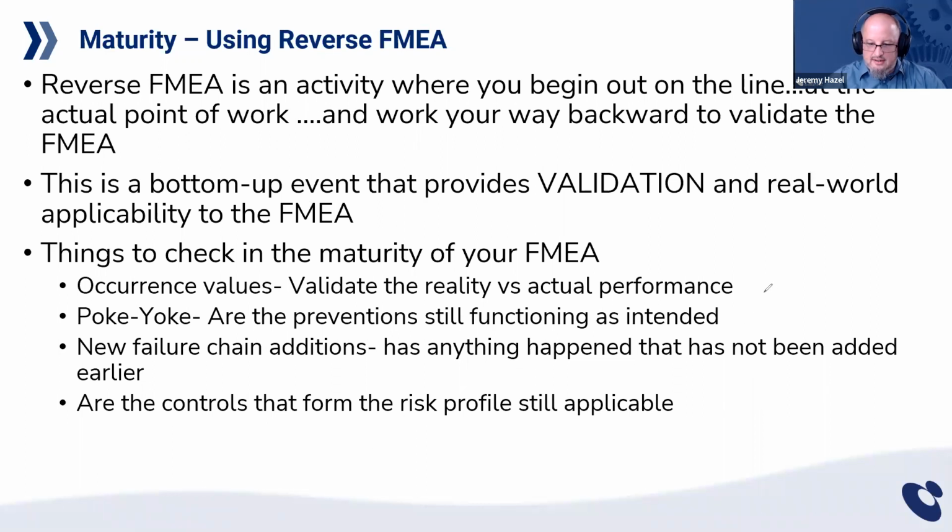Occurrence values. Validate the reality versus the performance. Poka-yokes, are they still functioning? Are they still being challenged? Are they working the way that you intended when you developed them? New failure chain additions, anything that happened that hasn't been added earlier.